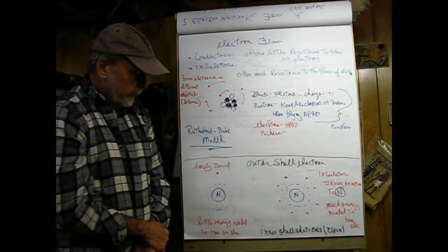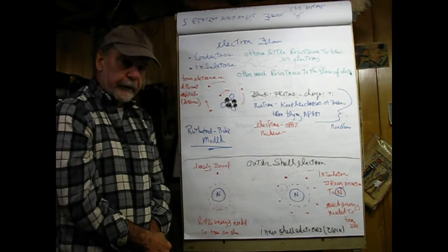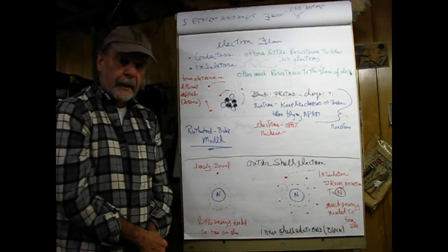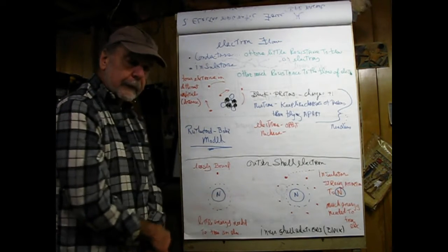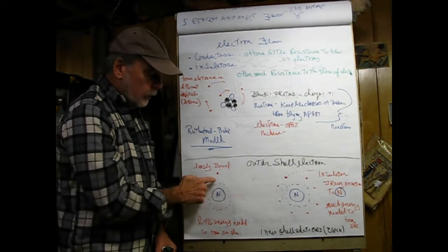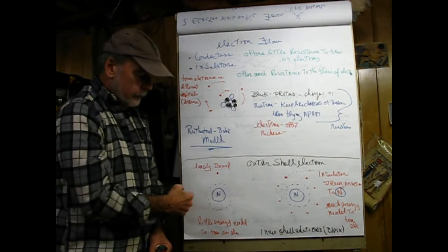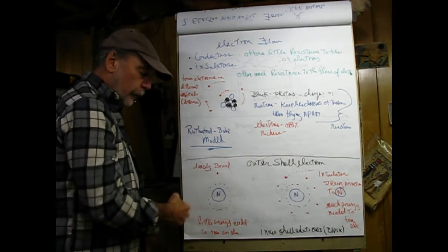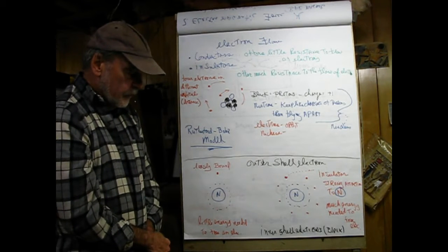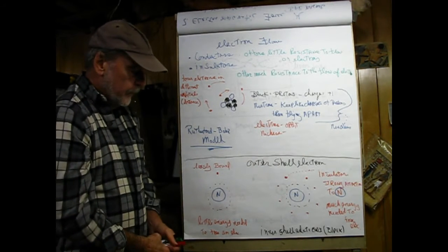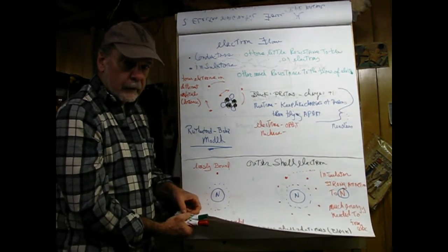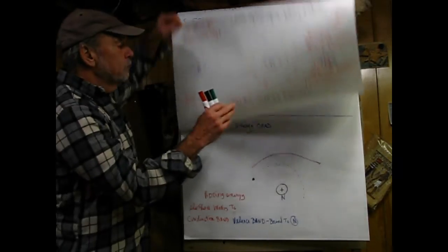Now on the other hand, a conductor, I'm showing this is one electron in the outer orbital, which is typical, is very loosely bound. So if we apply a voltage across this, this electron would not take much energy at all to hop over to the next guy, and the one here to your left would then come and fill this. So in a conductor not much energy at all is needed, and in the insulators a whole lot of energy is needed to free up an electron to conduct electricity.